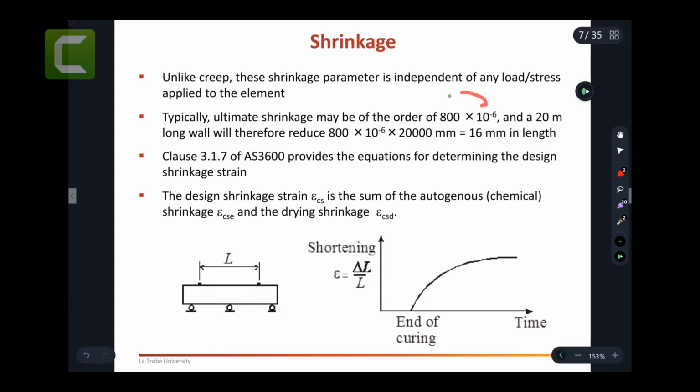Sometimes if you want to do concrete mixes in remote areas, and the engineers there will understand that this is not achievable, then they have to use maybe 700 or 650. They need to define this on their drawings or on their specifications. So things will be matching what's really going to be used and what's designed for.